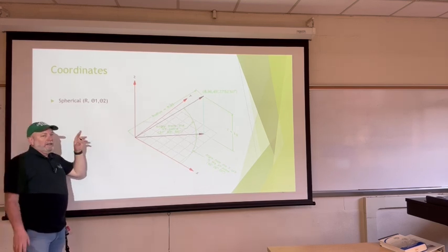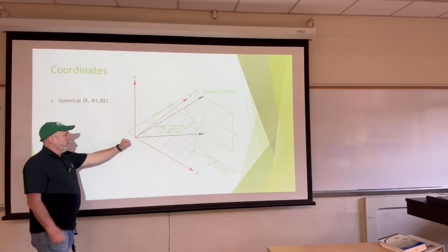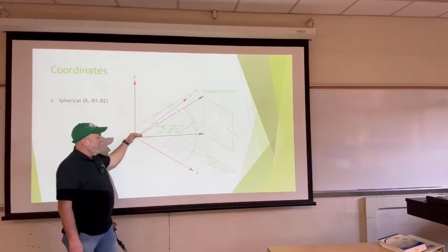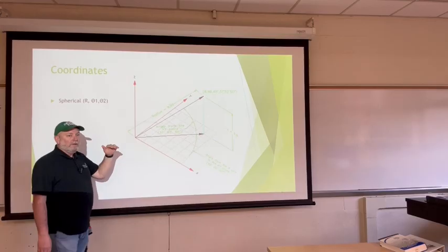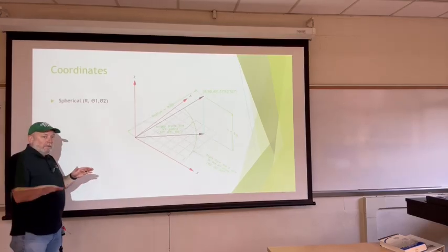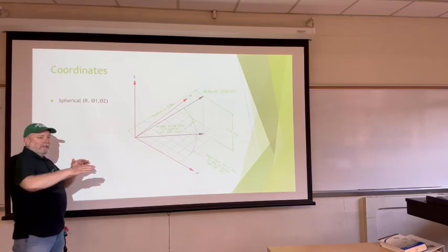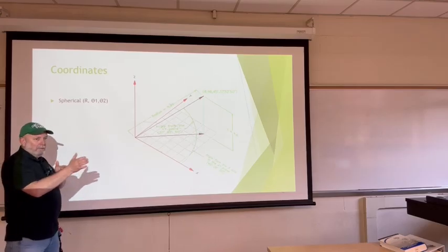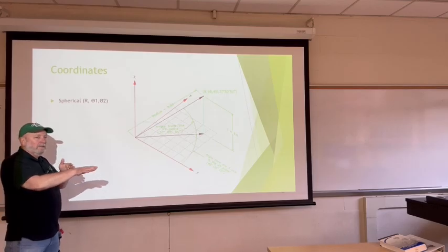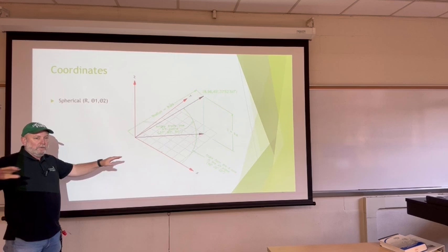Well, this is how latitudes and longitudes are derived from our geodetic datums. Our center point being like the center of mass of Earth. Our x-axis would be the equator. Our y-axis would be going to the pole. So we're measuring from, and our x-axis is along the equator. Well, where's 0 on that? Well, that would be where the Greenwich meridian would be. We're saying 0, and then we measure our angles off of that, east and west.